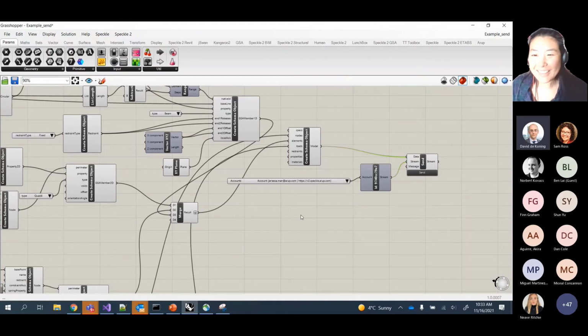If more info is added to the GSA file, say more load cases or more restraints, and then the information received from Grasshopper is updated, would the information defined in GSA get lost or only override the info from the stream? Yeah, so in GSA, the GSA connector will make a conscious effort to take a look at what's already existing in the file. And if there's anything existing, keep that. Or if there's something that's already been sent but changed in the data, change that. So it won't overwrite, it will try to merge with what's there.